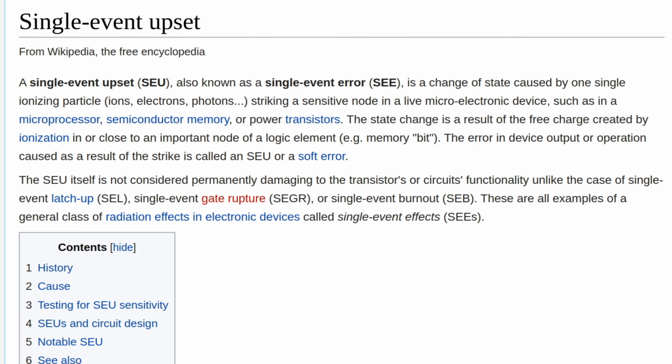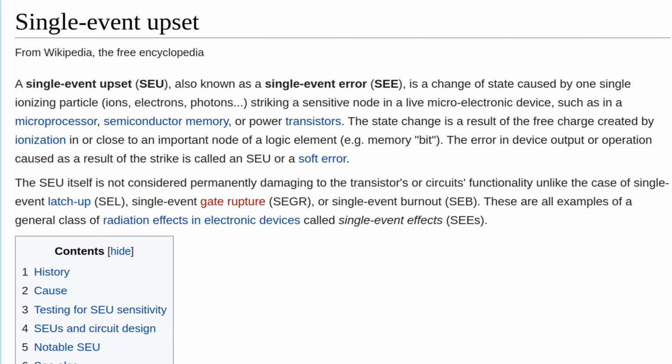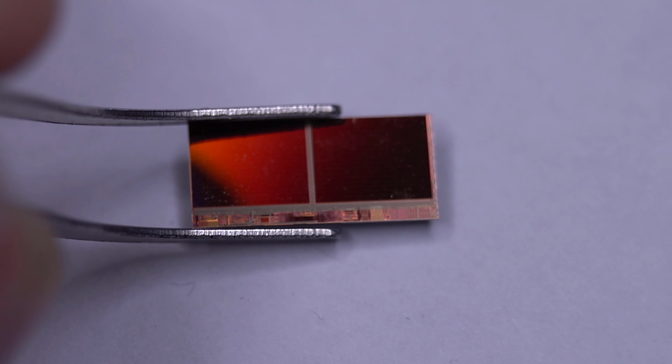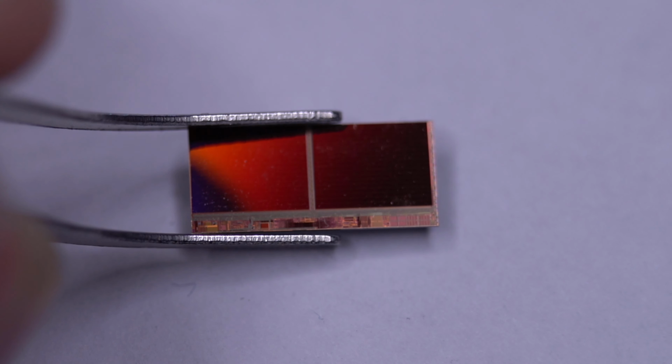The precise physical mechanism by which radiation can flip bits in memory depends on many factors. In academic literature, bit flips due to radiation are called single-event upsets. The physical orientation of the silicon chip in relation to the radiation source would have a dramatic effect on the rate and mechanism of single-event upsets. In the case of cosmic rays from space, if the surface of the chip was oriented towards the sky, this would maximize the rate at which single-event upsets could occur.